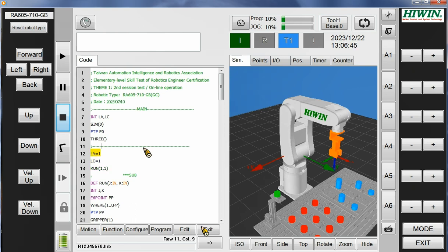That means layer 1 on tray C and tray A. And here, please do set this command line, because the maximum speed for the robot is so fast. About automatic mode, the speed is 2000 mm per second. So here we reduce the speed to 10%.